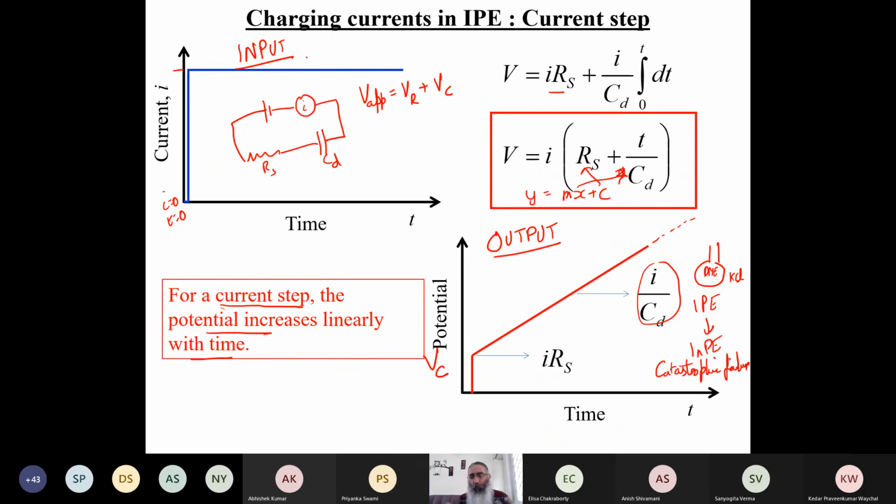The dielectric starts to break down because you are transferring charges from the electrode to the electrolyte. The electrolyte in this case is the dielectric. So the dielectric starts to break down. It starts to change chemically, and therefore the capacitor is no longer the dominant player in that picture. The capacitance is going to completely vanish in a perfect sense. In real time it doesn't perfectly vanish, but in an ideal world it completely vanishes, and that is what is referred to as a catastrophic failure of the capacitor.